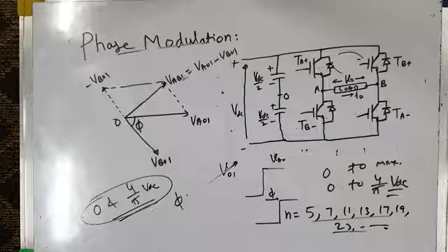Okay, and then we have seen how we can go for minimizing weighted THD of voltage by choosing the locus of the point in such a way that V5 and V7 are kept as low as possible.